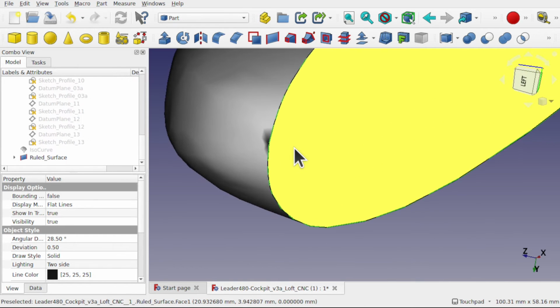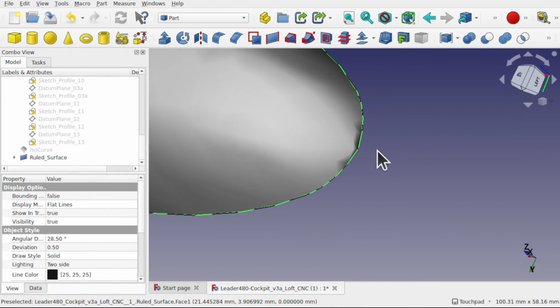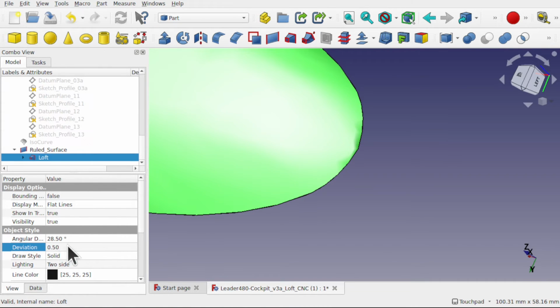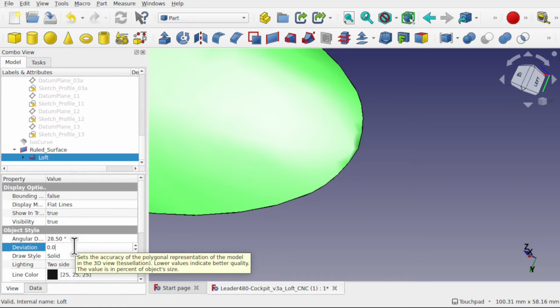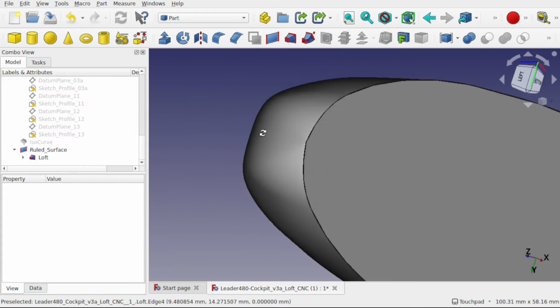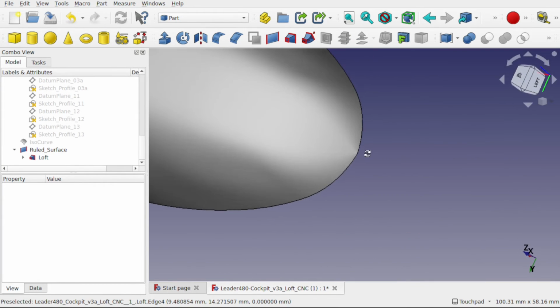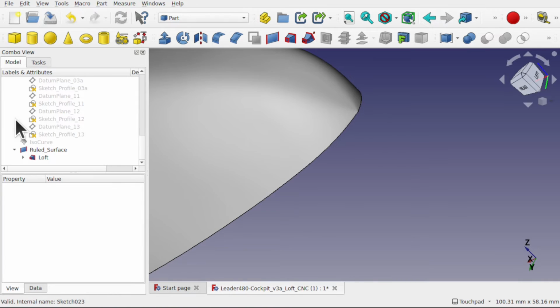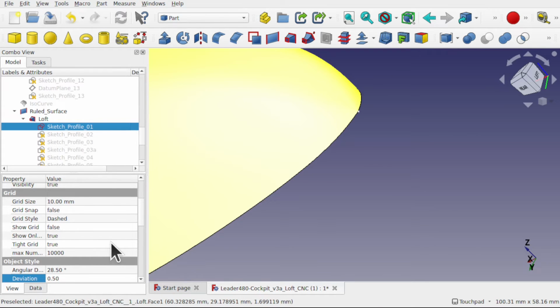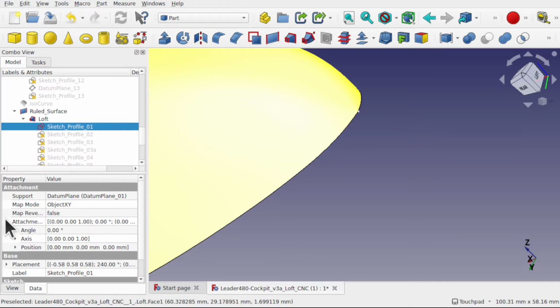I can see we've got some puckering at that point there. So let's just check that loft deviation, 0.05. That's better. And I can play with that profile, that point, you can see just there. And we may want to set the position, because it's attached, it belongs to Z, so we can move that.